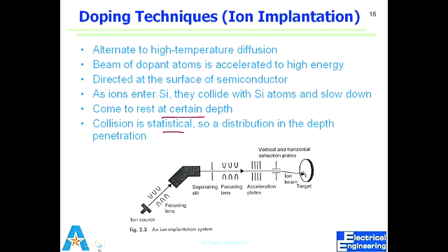So ion implantation is essentially bombarding of ions from an ion gun onto the surface. In this case, you see the word lens, but using ions. Lens is nothing but these bunches of coils which focus or change the beam, right?